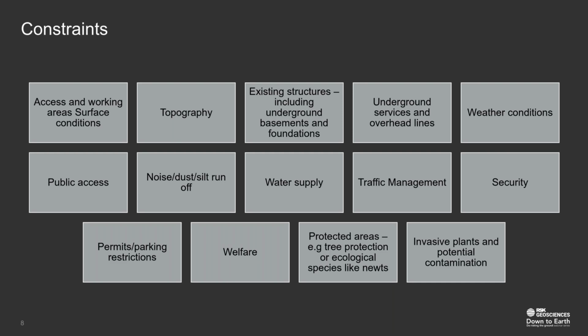Do you need any permits, or is there any parking restrictions? So it might be that you need permits to park on the street if you can't access your site. It might be that your site entrance is very constrained on a single track road, and actually you want to put some parking restrictions in so you can add the turning circle of a larger vehicle to get into the site. Do you need any welfare, or is this available on site?